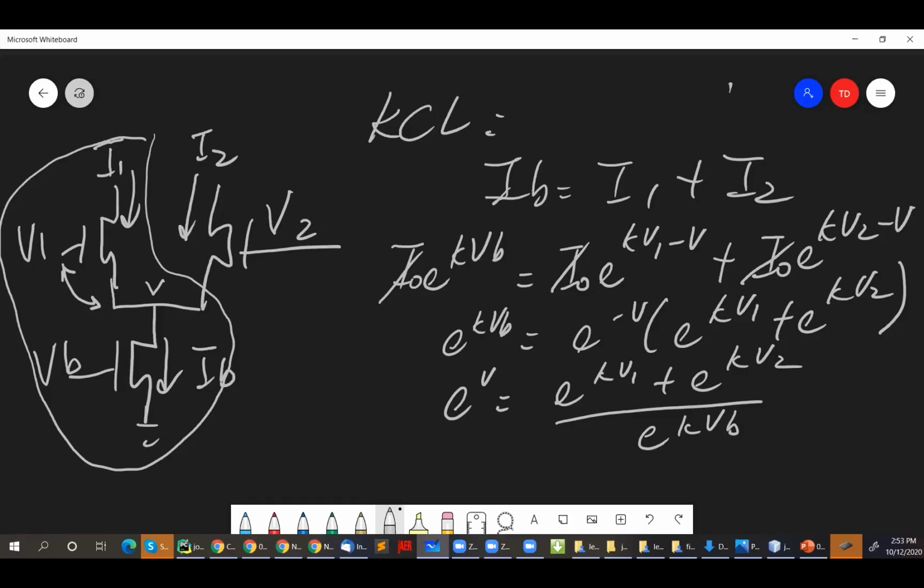Oh no, of course kappa cannot be 1, but if you want to have an intuition about a circuit, sometimes you don't want to put in all these numerical values. So you're going to assume that kappa is a constant anyway, even though it's changing as a function of gate voltage. But if I just want to have an idea of the functionality of the circuit and to make things easy, like, is this circuit a source follower or not?